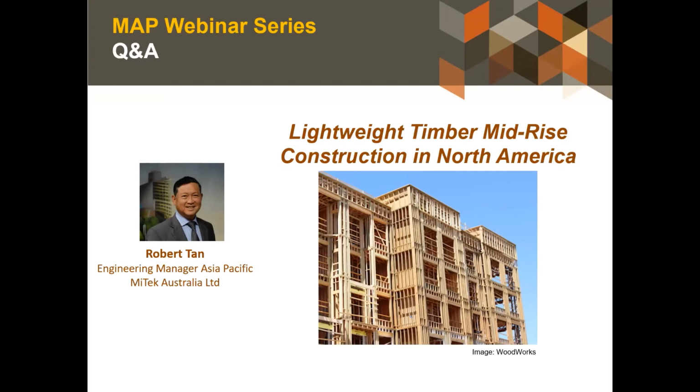Yeah. I think it's also fair to say that, particularly in the US, the bracing system calculations are a little bit more comprehensive. Like in Australia, we use AS 1684 for residential construction, and it's very basic type calculations, whereas they go into a lot more detail on distribution of forces and everything like that through the different bracing walls over there.